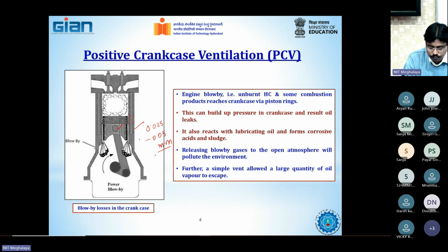This very small gap has been kept between the piston and the cylinder to safeguard their life. Because of this gap, the piston and cylinder do not lock each other. In between, there will be a very thin layer of lubricating oil, which will lubricate the surfaces of piston and the cylinder.